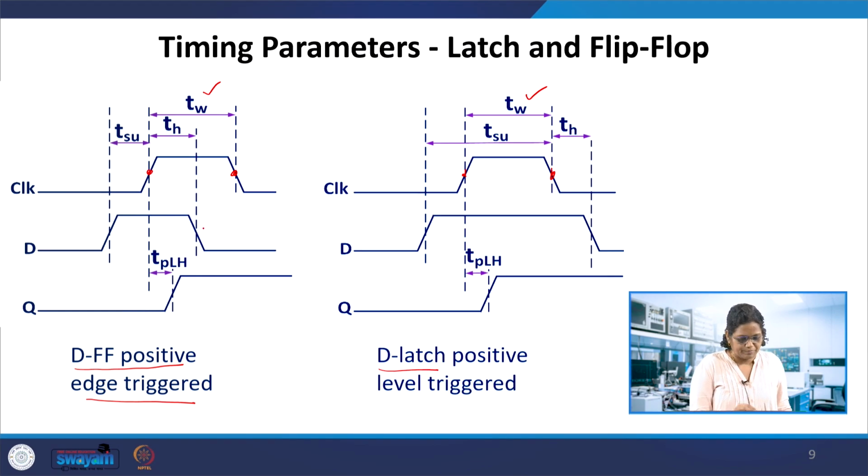So for the setup time and hold time of the flip flops, we said the data is changing over here. The setup time of this flip flop is from here to here. In this duration the data should remain stable. A data change can occur away from the clock edge, but it should not be near the clock edge. So that is the setup time.